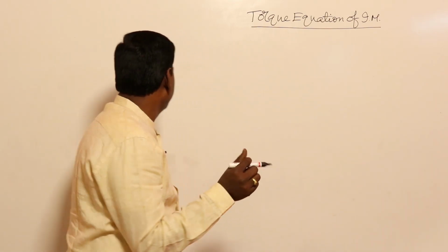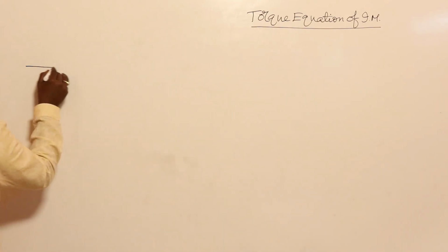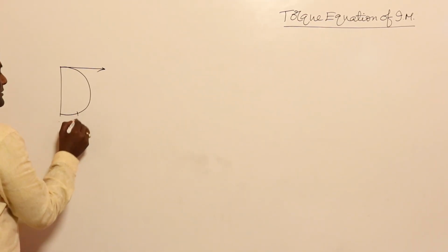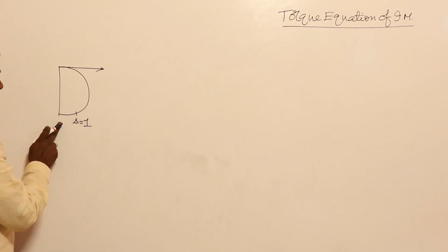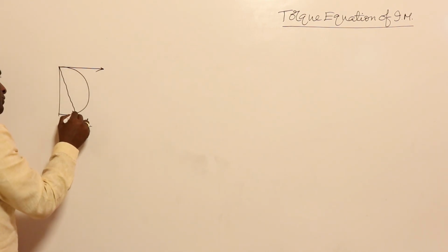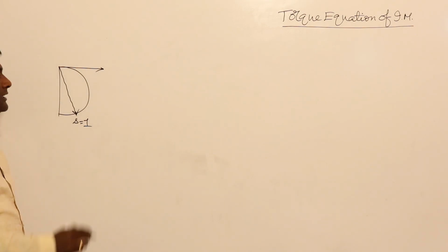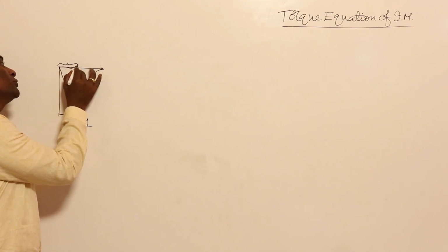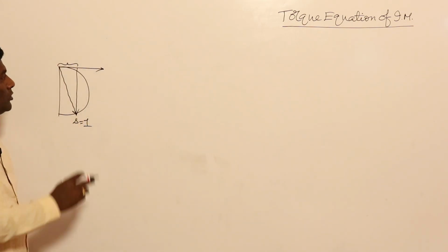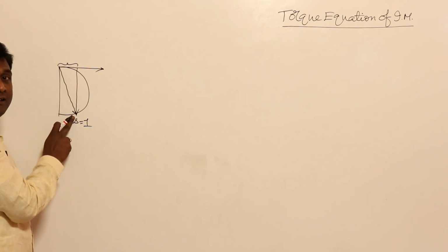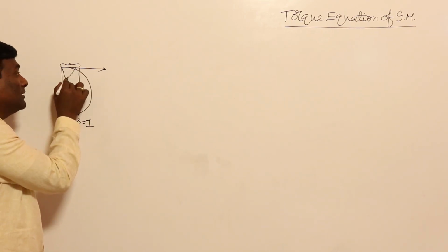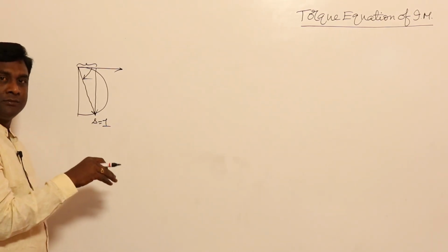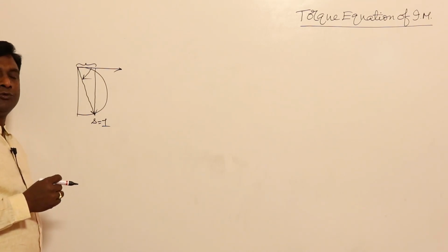Because if you think of an induction motor from the rotor point of view, for example, S equal to 1 here. If S equal to 1 is here, this is going to be the starting torque, starting current. If this length is the starting current, how much is the torque developed? Torque developed is going to be this much. The magnitude of starting current is high, and the starting power factor angle is high, so power factor is going to be less. Power factor angle is more, so cos of more is going to be less.